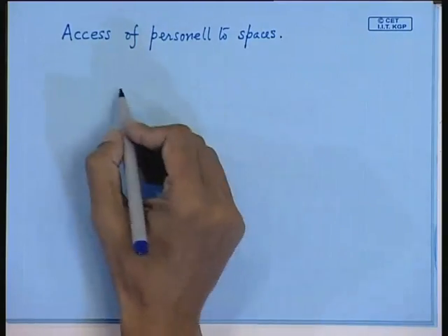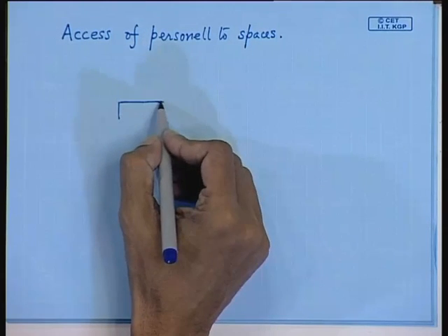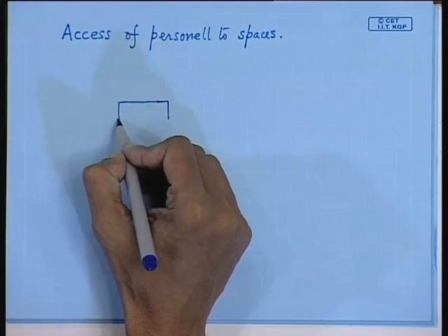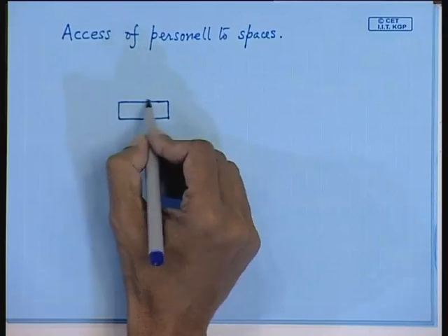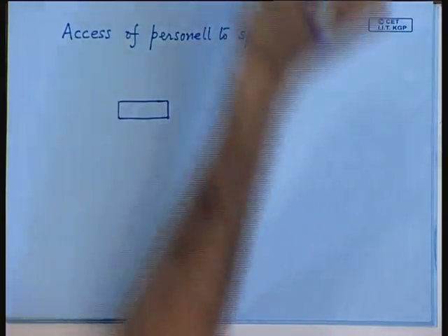So, remember that suppose in your engine room or machinery room you have some machinery. Now, I have seen naval architects who do not provide enough space for people to service the machinery. In a ship's main engine, you do not have enough space, that is, you cannot walk around the engine or lift out the components.